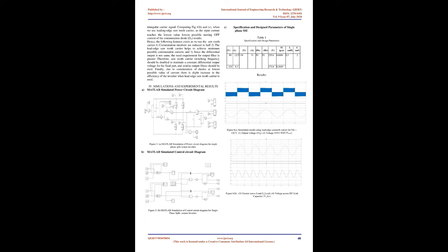As shown in Fig. 2 and 4A, for single-phase SSI, diode DX is always conductive and DY commutes at various values of current for half the fundamental period. This can be demonstrated during a single switching process with 3 separate states as below. The first turn-off depends on the lower envelope intersection point defined by min(Vx, Vy) with the carrier signal, which occurs with different current values during the charging process.